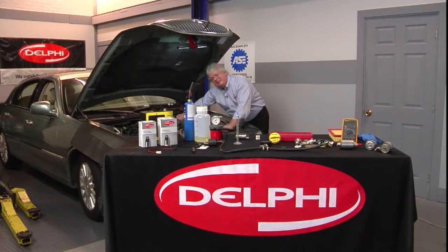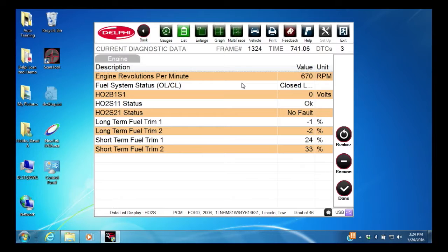So mass airflow sensors, you see the low trim numbers, negative, pull a vacuum leak. If the numbers come up, and they really did, and the O2 goes down, then you've probably got a decent O2 sensor to work with. Now it's time to go looking for why it was rich.